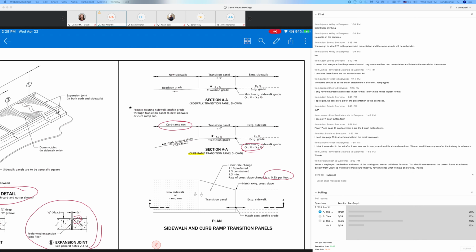You don't do that by the ramp, because if you think about it, the curb ramp elements are the running ramps to the turn space, and the turn space comes to the, if it's a combo or others, and then comes to the running ramps and the curb takes you out. You can't warp the ramps. The ramp should have a constant cross slope less than 2%.